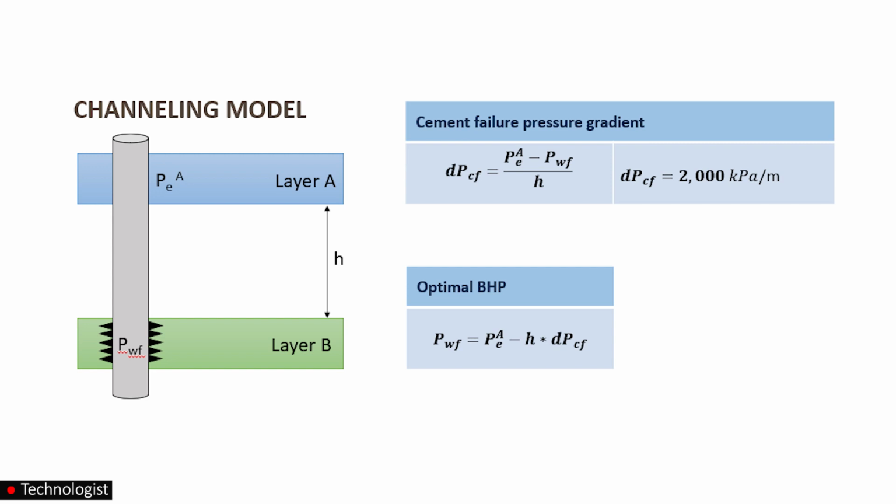I have analyzed the sections, namely open hole data, and concluded that in case of the producer wells, we have a minimum shale break of 5 meters, and based on the formula, we can lower the pressure at producers to a bare minimum of 45 atmospheres. And at injector wells, the bottom hole pressure currently can reach 228 atmospheres.